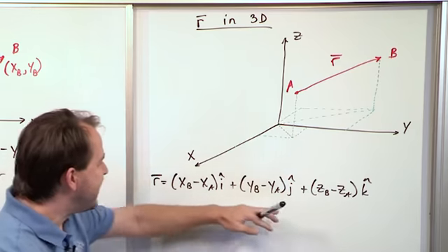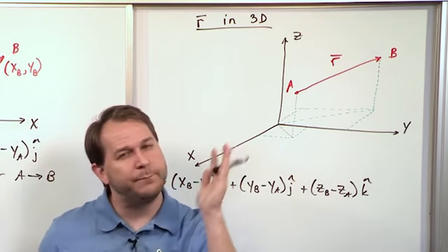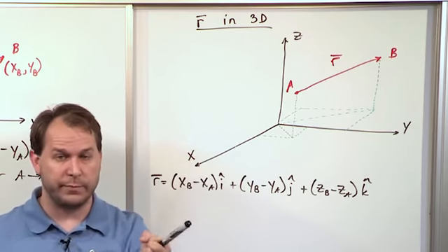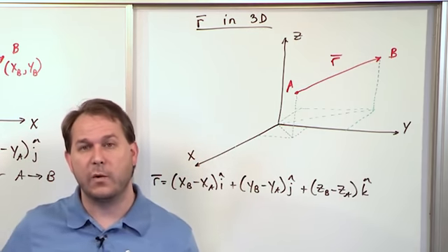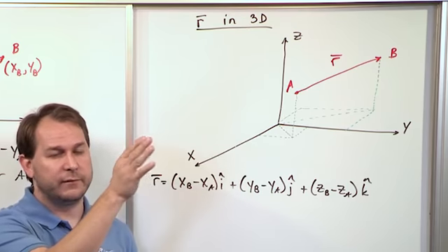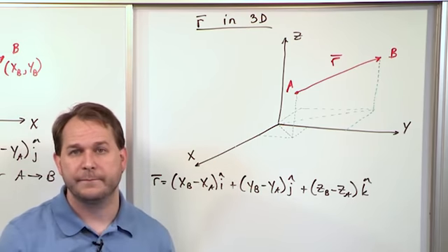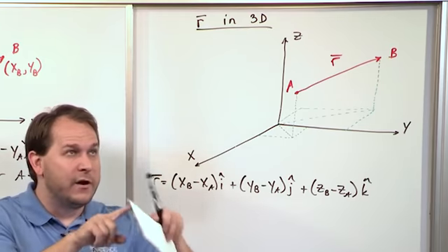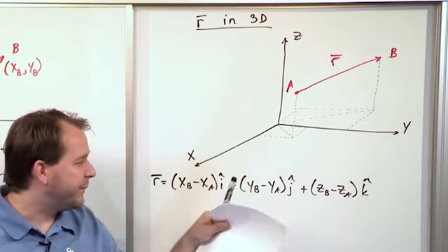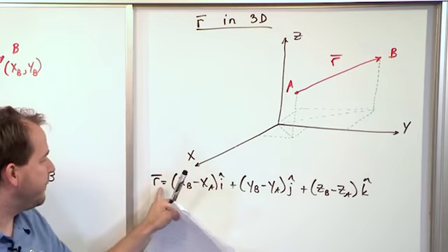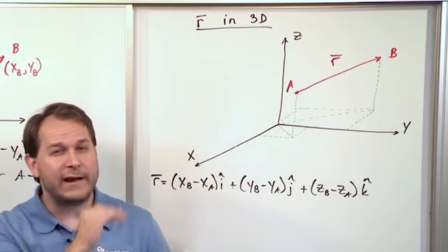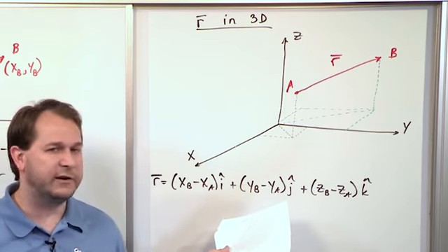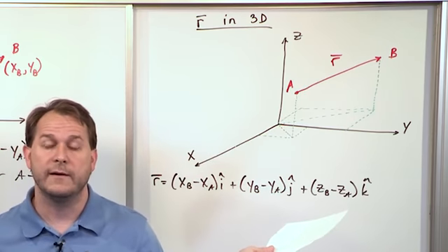The direction is now governed by this, because if I have an anchor in the ceiling with a rope, and let's say that the origin down here is in the corner, x, y, and z, then I know the components or the coordinates of the anchor point. I know the coordinates of my hand. That forms a line segment, and from this I can figure out a position vector in 3 dimensions, right? So I can actually figure out the direction that that force is pointing just by using this equation here if I know the components of everything, right?